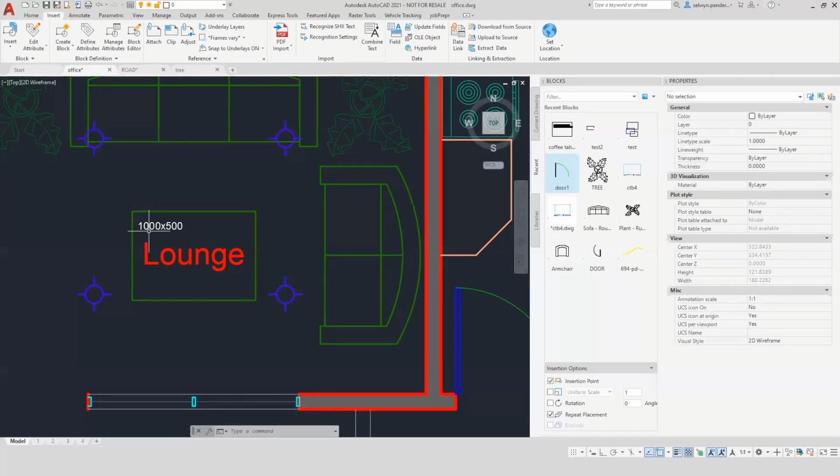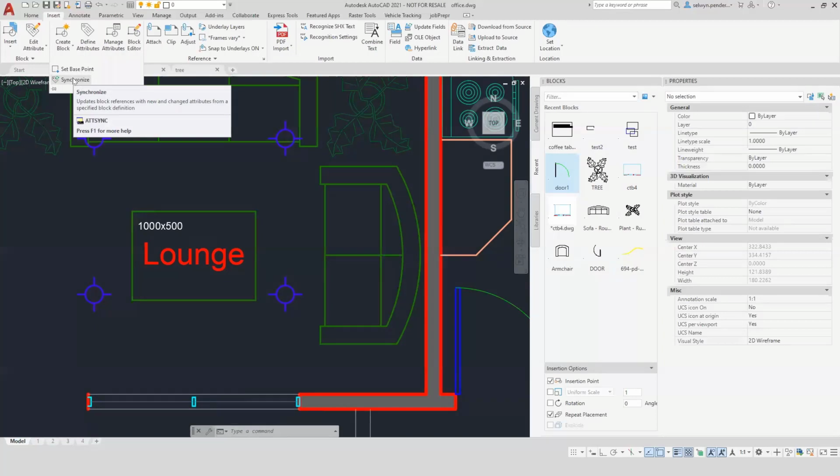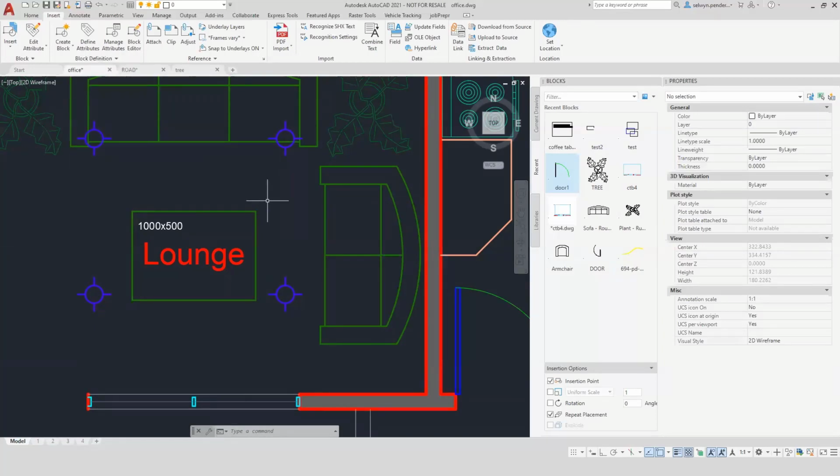Sorry, just wanted to capture it whilst you were just talking about the sync. The question is, will the attributes sync if you were to close and then reopen the drawing? Yes, they will. Yes, because the block definition has been updated in the database. However, the visual drawing editor hasn't been updated. So the definition is in the background, and when you reopen your drawing, the blocks will all take on the qualities of what's in the table in the drawing.